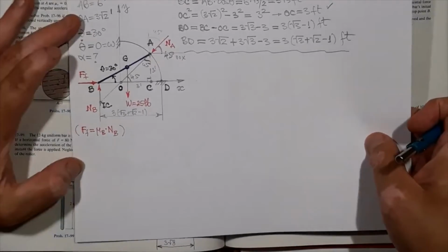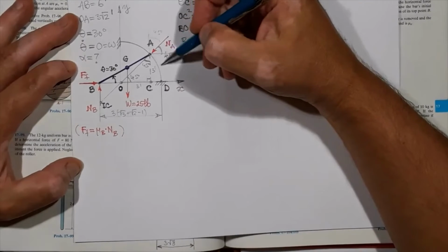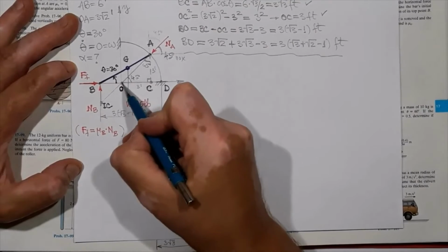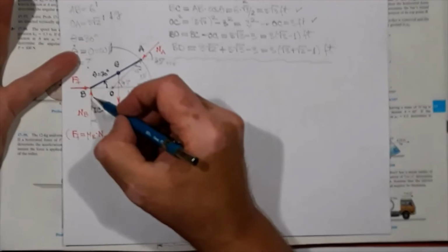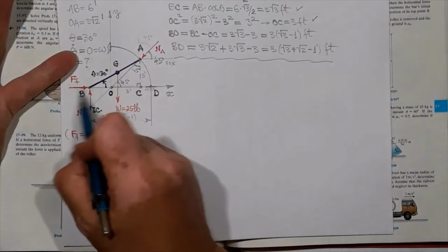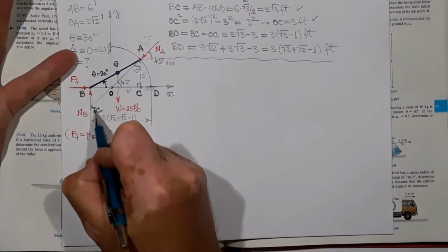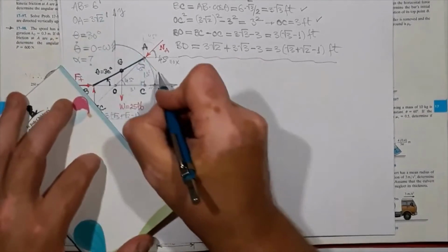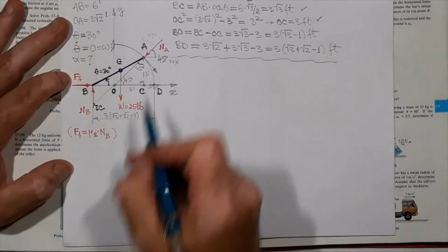So let's start with the instant center. I have the velocity of A is tangent to the path. The normal to the path is from A through O extended because it's going to be perpendicular to the velocity. And then I'm drawing the line that's perpendicular to the direction of sliding of B. The velocity will be along horizontal. And where the two intersect, there's the center. I'm drawing here quickly the vector tangent to the path at A.